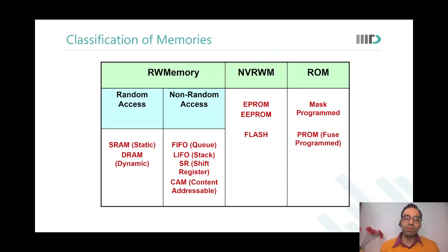So this is about the access pattern. They are random access memories. What does random access mean? We can write or read from any particular location at any particular time. I will give an address to the memory, and I can read or write any location. So where are SRAMs? The DRAMs we already discussed. SRAMs would typically be used as caches, for example, L1 cache, L2 cache, and so on, where you have an instruction which may carry an address and you want to write at that address.